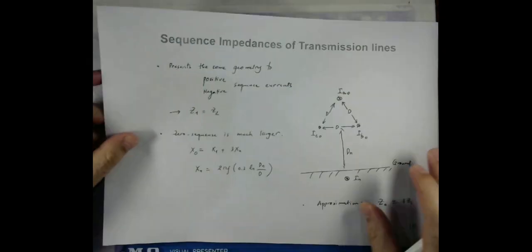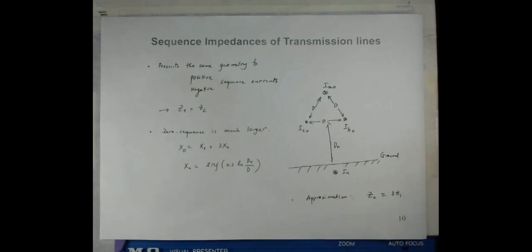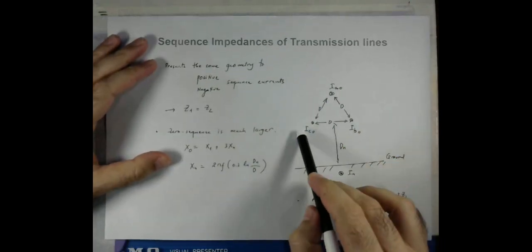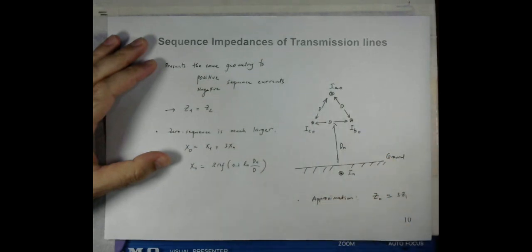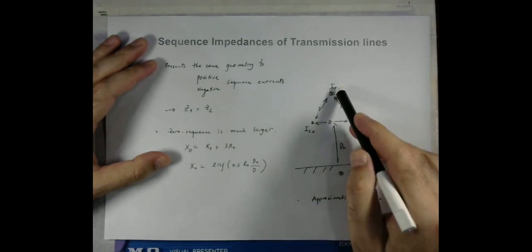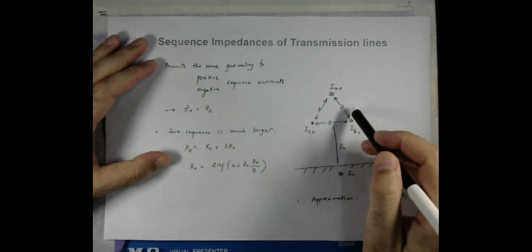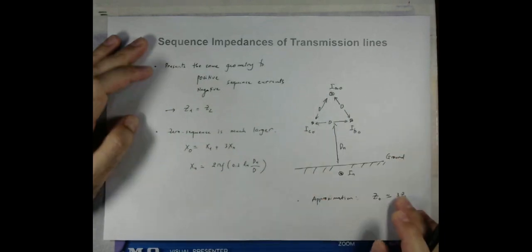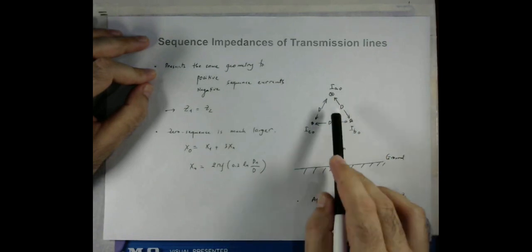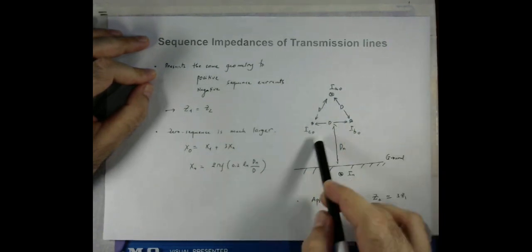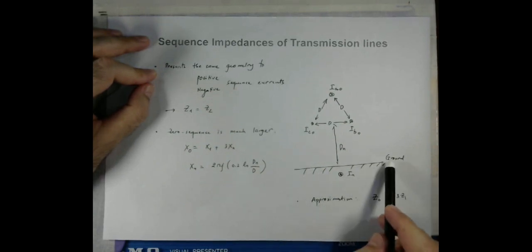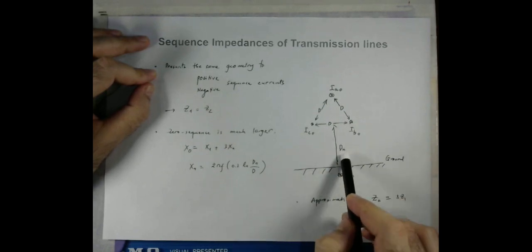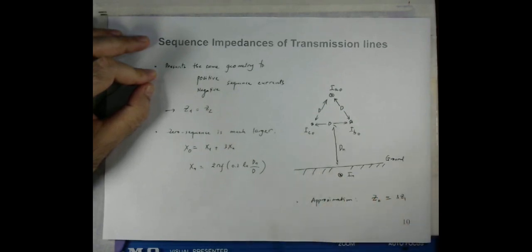So the case is shown here. Three phase transmission lines, where we are talking about the zero sequence currents, and it is mentioned here that these are the three transmission lines. Let's say this is the ground point, where the potential is obviously zero, and this is the distance dn, which is the distance of, let's say, the transmission line to the ground.